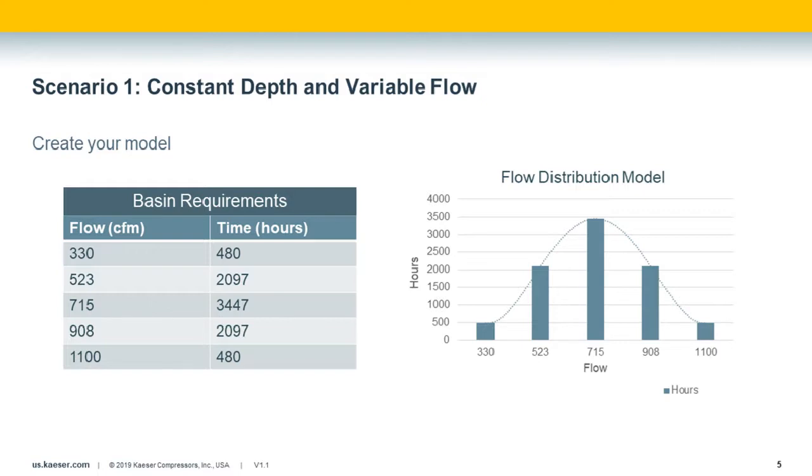For a more realistic evaluation, we can apply a distribution curve for our flows and assign the expected hours of operating for these points. If there is no history for the process, we can take our Gaussian logic and create a profile and apply values. Note that we do not need to be too religious about the application, and if you know the relevant design points, use those points.